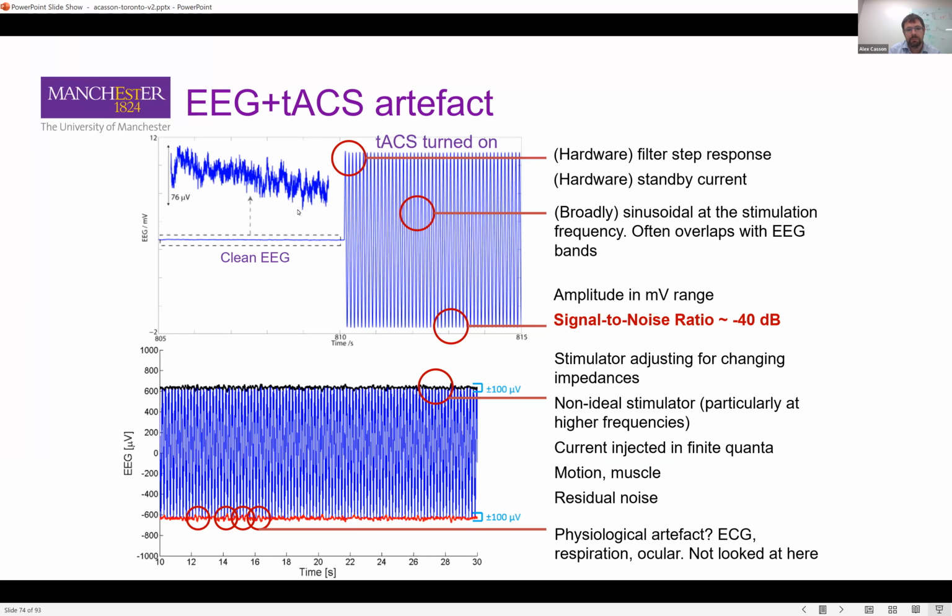And yeah, just to put the problem in context, this is a standard EEG signal. This is what the artifact looks like once we're doing the electrical stimulation. And the signal-to-noise ratio is about -40. It's rare you see other biomedical engineering problems with such a low signal-to-noise ratio. There are one or two out there, but it really is a challenging artifact removal case.